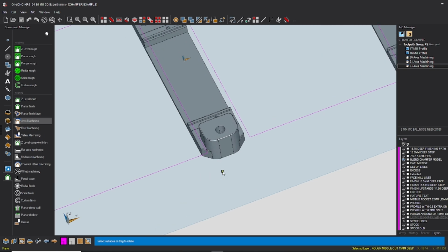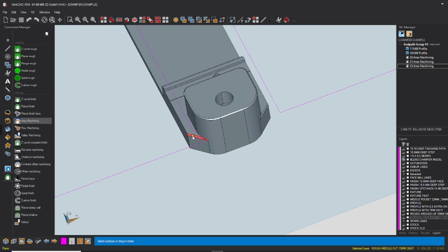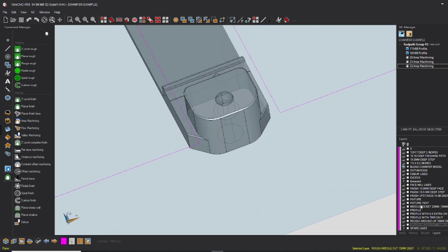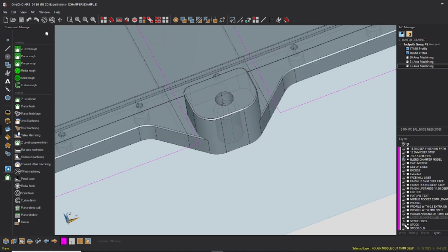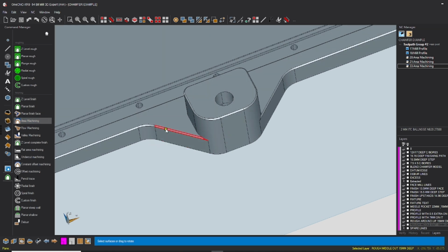machining, for instance, if I highlight that there, it's going to select that whole bit on the model that I'll show you. Stock, turn that off, go area machining, look, it selects that whole edge. And I don't want to machine, lucky for me, I mean you could do that, but I don't want to machine, you know, 70% of that. I only want to machine this bit here, and that's what it's about.